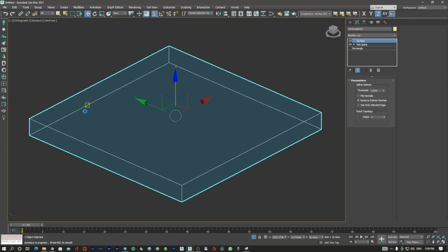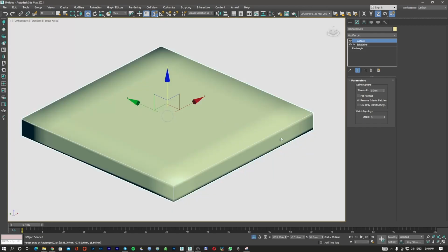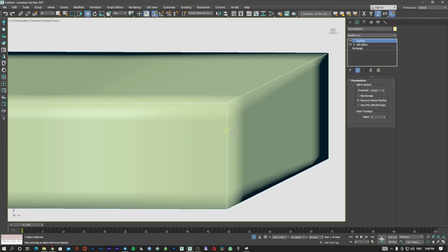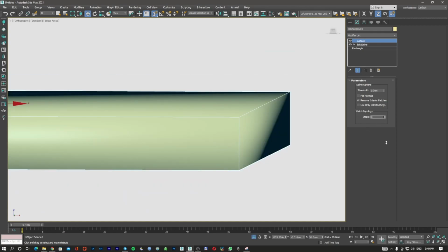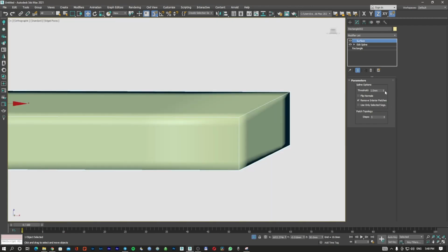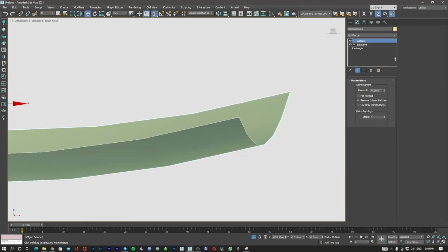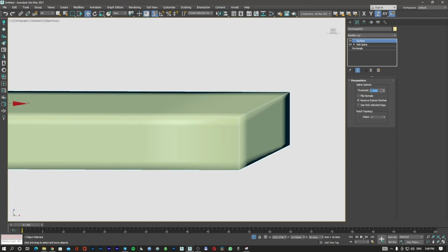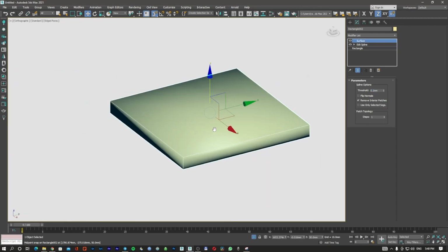If you're trying to make surfaces like Zaha did in architecture or other this kind of curvy architecture, this is a very good method to use. So as you can see, they are not perfectly straight, because I can tell it how many steps I want to have. The threshold is just saying how far these points are, and I'm going to say 1 millimeter, but I can have even less. And the steps of the object.